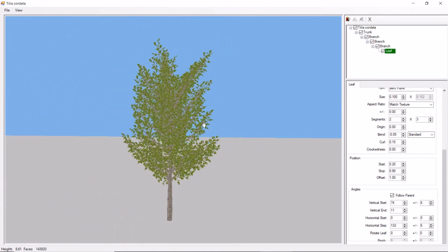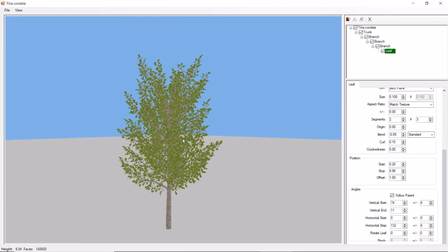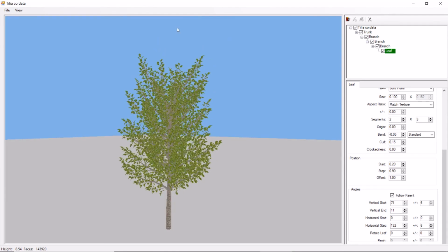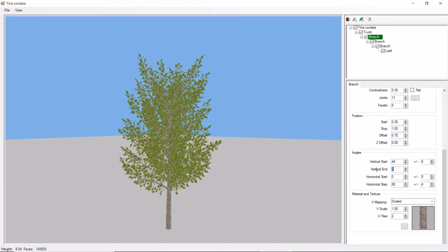Well, as we can see, the top part of the tree hasn't been sufficiently covered, because with the curvature pattern we've indicated, we can't achieve more verticality in the upper branches, even with the minimum value. So we're going to create another branching from the trunk to achieve the conical shape we're looking for at the top of the tree. To do this, we're going to make a copy of all the previous branches. We can do this with a click on the level from which we want to copy, drag it to the trunk in the diagram, and release.